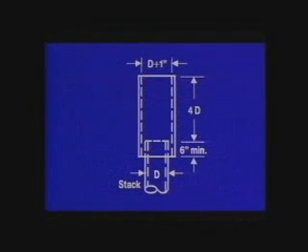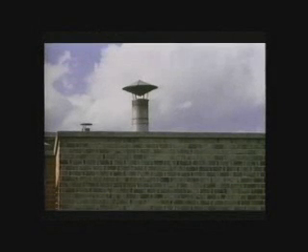Rain protection is often used. This illustration shows a slightly larger diameter duct mounted on the exhaust stack. Rain never falls exactly straight down, so when it hits the inside of the larger duct, it drifts down outside the stack. To avoid re-entrainment, don't use the slanted rain cap if the stack is close to the air intake for the building.